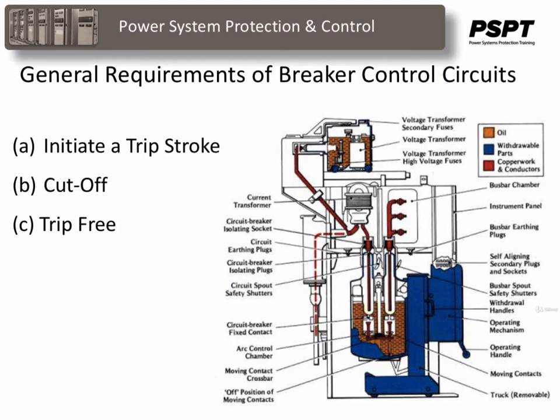Solenoid-operated breakers are sometimes provided with a collapsible linkage. Pneumatically operated breakers may be equipped with two latches, one of which is unlatched during normal trip operation and the other is only unlatched for a trip signal when the breaker is closing. Other breakers use large dump valves to quickly exhaust the air under the closing piston.